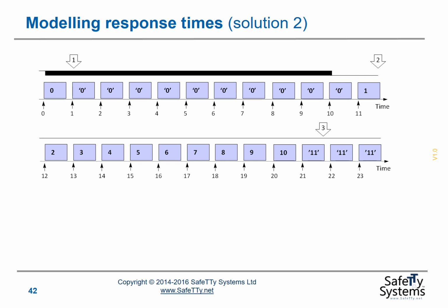And that means that the code that's counting up how long the switch has been pressed for may be continually reset during that 10 millisecond period. So we can only begin to count up to our threshold of 10 after the switch stops bouncing.